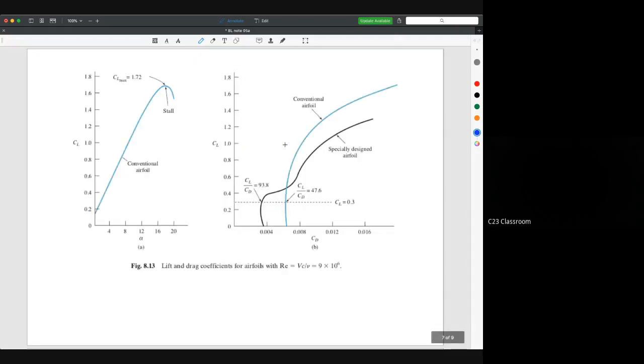So this is another example. The idea is the lift and the angle of attack. The bigger the angle of attack, the more you may increase the lift force, but at a certain point a stall happens. Stall means your airfoil may lose its lift force, so then it maybe cannot continue to support your flight. Your flight will lose the ability to fly. So this is a very critical point, and in aeronautic engineering, they are very alert about this.